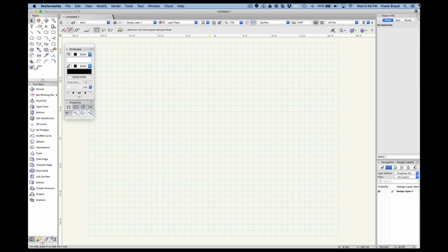Control of what objects look like, or object attributes, such as color, texture, hatching, and line weight, is managed by the organizational drawing structure called classes. This is one of the two main drawing structures in Vectorworks. The other structure is called layers. All objects, whether nested or within other objects or at the top level, are each on a layer and in a class. The primary purpose of both layers and classes is to control the visibility of their members.